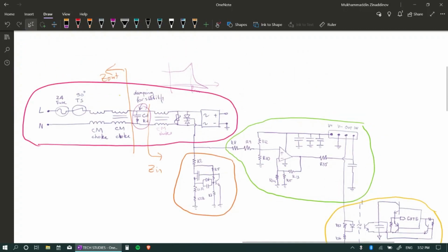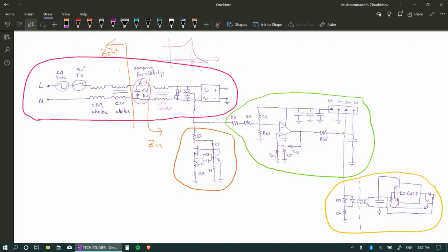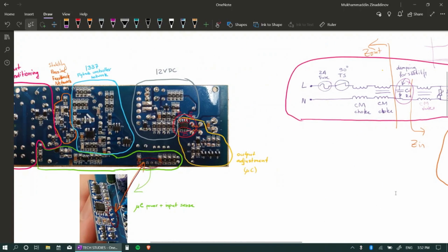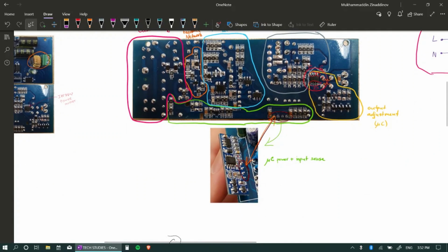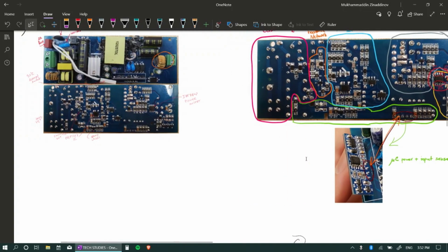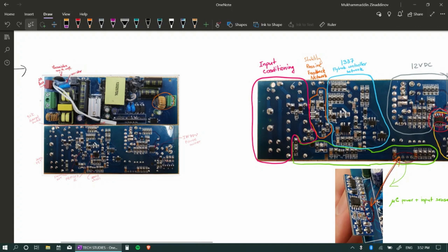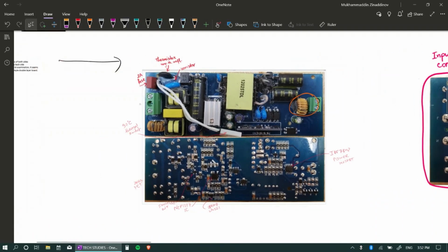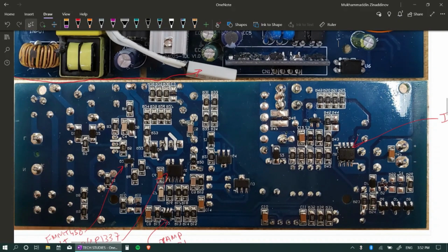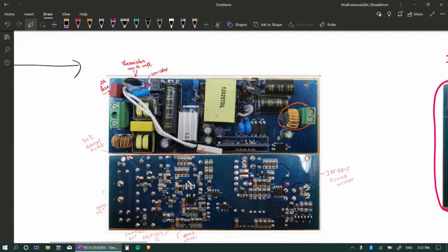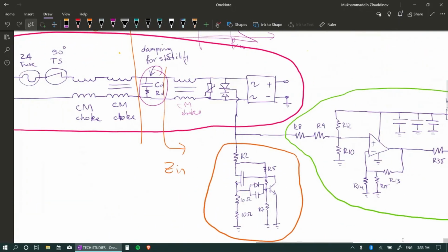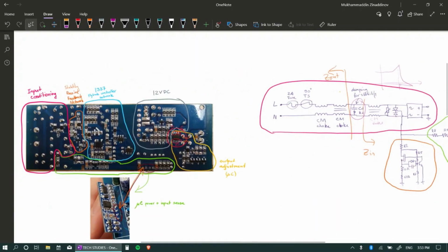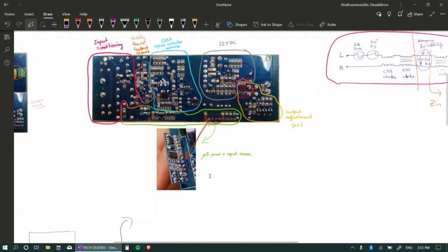So now we're completely ready, if we choose to do so, to go into more detail and look at what motivated the choice of all of these transistors and components, with aspects like heat dissipation. For all of these capacitors, when you're choosing, you need to look at their ESRs. You need to make sure that there is no crosstalk for all these paths. So there are a lot of details that go afterwards. After you are at this stage, when you have a general understanding of what the board is doing, you can go into the more nitty-gritty details of the device operation.